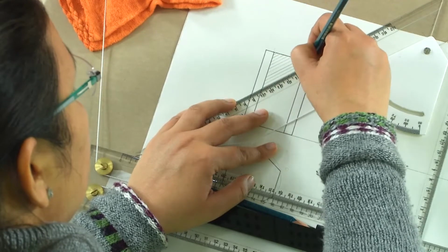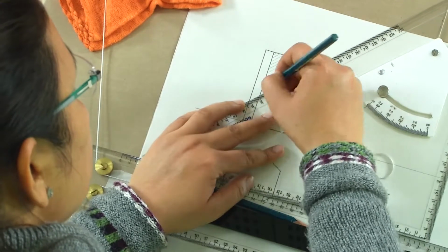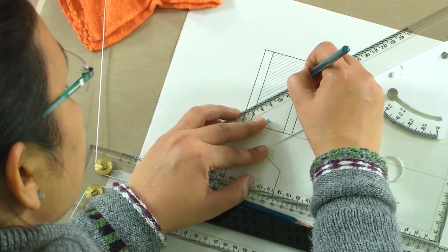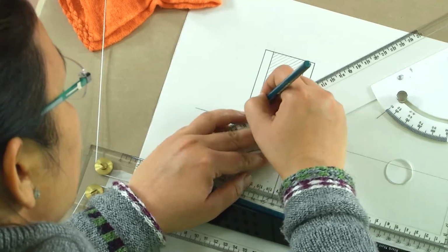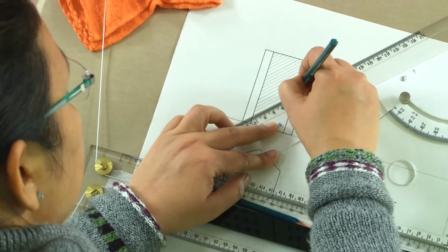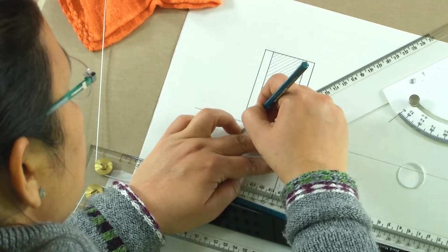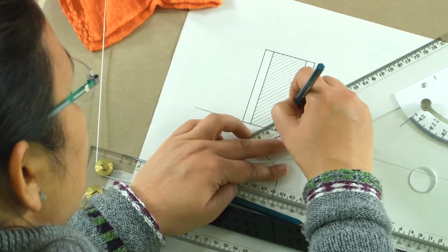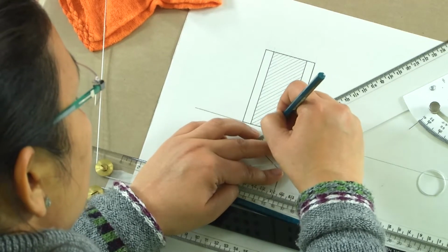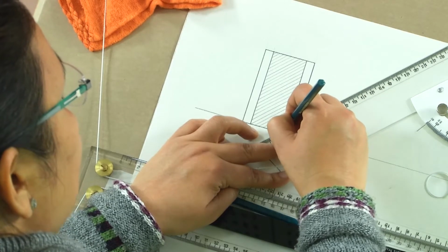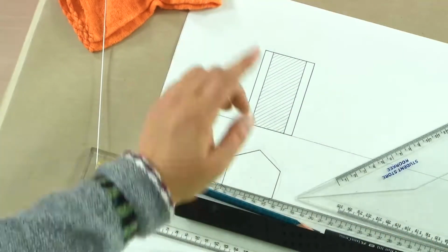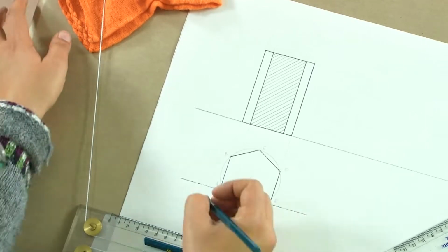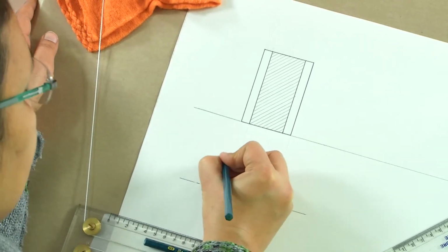this surface is cut. So, we will draw equidistant parallel lines, and whenever we are drawing on one sheet, we will retain the angle of hatch preferably. So, if we are choosing a particular angle, for example, I am choosing 45 degree here, preferably we should be keeping the same angle. This is not mandatory, but then it makes our sheets look better. So, while we have to work on technicalities, we also have to look at the aesthetics. So, this is the section, this is the actual object which is left. So, we will only darken this remaining portion.